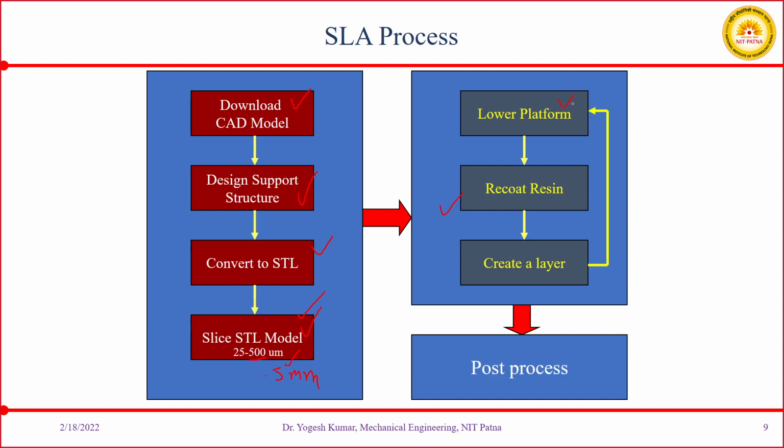As soon as you lower your build platform, the fresh liquid resin comes on this build platform, and after this you move your laser on this thin layer of liquid resin, and due to polymerization it gets solidified, and your layer is created.